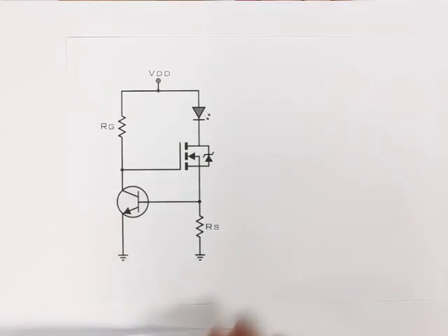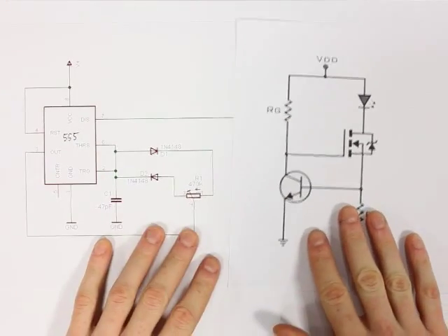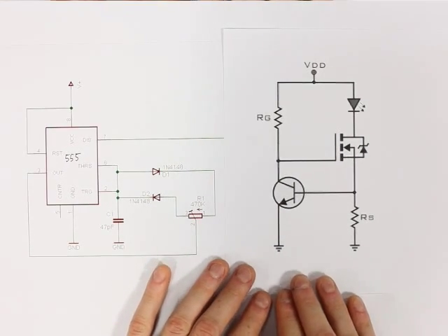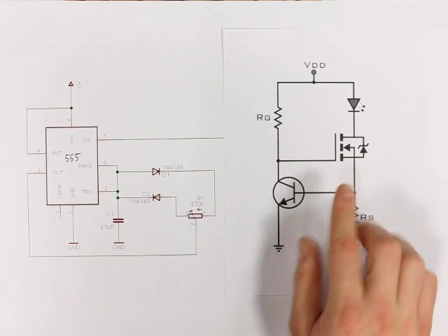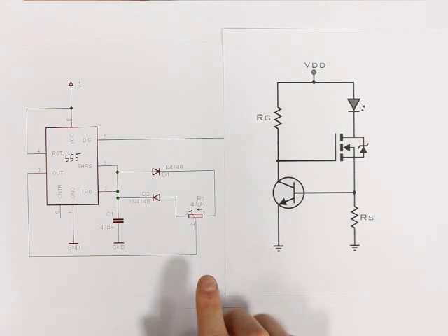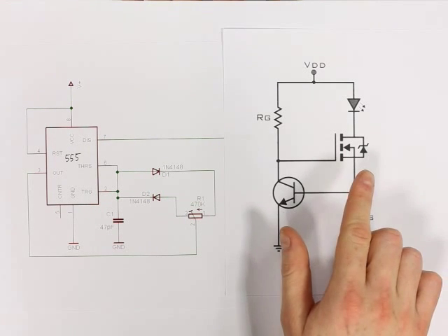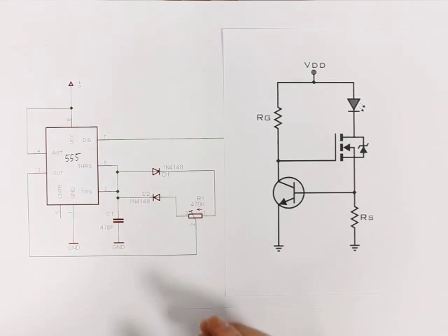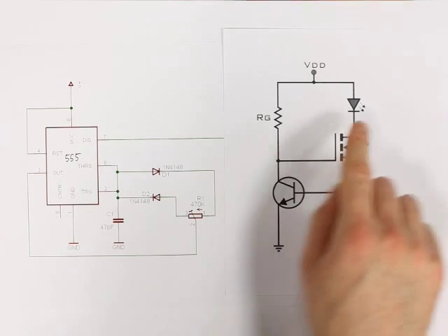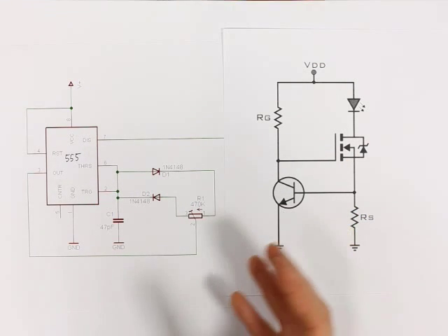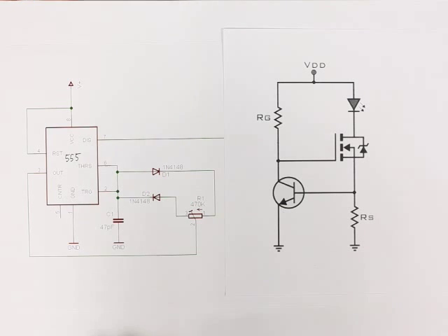And finally, we added pulse width modulation, hooking that in to the gate of our MOSFET, and that allowed us to run the LED at less than 100% power. It didn't give any improvements in energy efficiency at full power, but it was very useful if our LED was too bright at full power, or for example, if we were implementing a torch or a flashlight and we wanted a power-saving mode of operation. This would allow us to run our LED at 50%, 25%, 10% light output and save pretty much power proportional to the reduction in brightness of our LED.